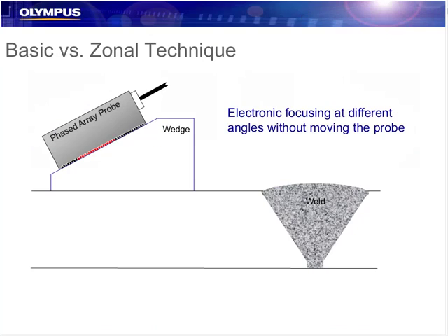When we look at some of the pipeline requirements, here we're looking at a typical weld that we're used to with a bevel of 30, 33 degrees, something like that. Typically for the general weld inspections that we are probably more familiar with using sectorial linear scans, we choose a number of elements and we can fire a sector scan, focus on the weld, no problem getting the proper incidence angle here. And we can electronically change that and get a full volumetric coverage and good detection of our defects.